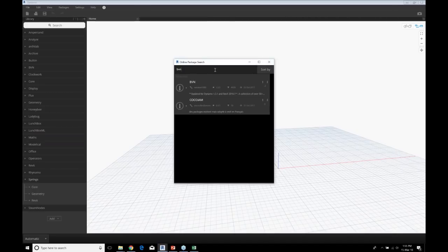So I'm looking at ways that you can quickly change standards or naming conventions. An example of that could be around walls. You might document it as wall type 1, but potentially with Dynamo, you can extract all that information and rename it based on layer build-up: 10 mil gyprock, 90 mil stud, blockwork, whatever.